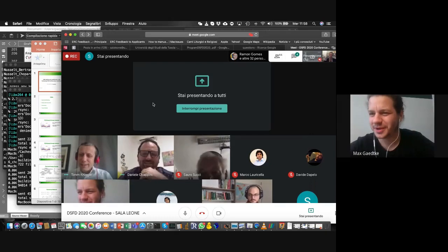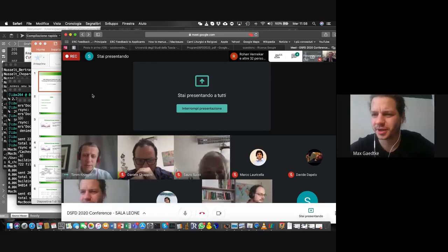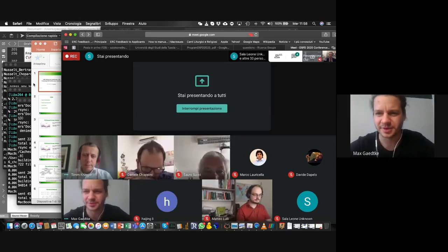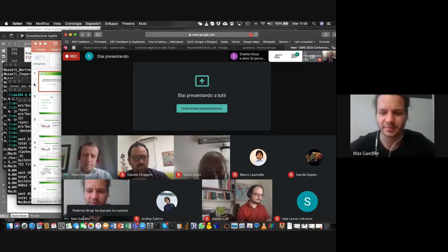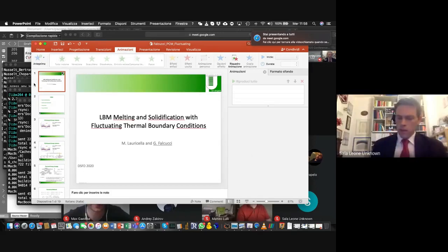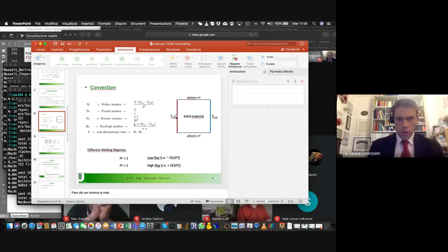Okay, my one is a quick one, I guess at least. What kind of boundary conditions do you use for the temperature, and have you made sure that it works in a transient way? So not all boundary conditions in Lattice Boltzmann are easily applicable for transient boundary values. This is a very good question. Thanks very much. For the hot wall, if I do understand well.